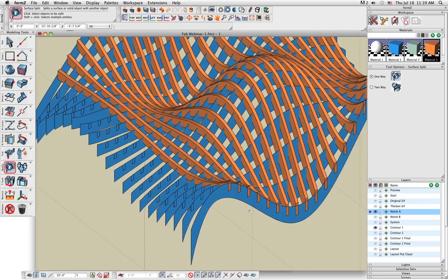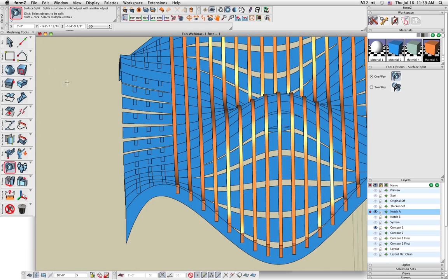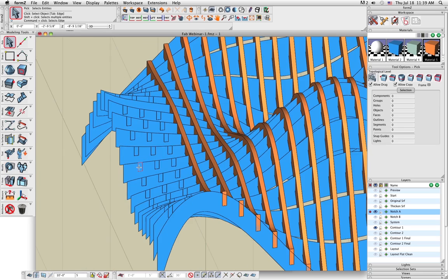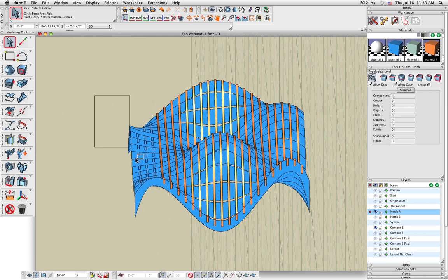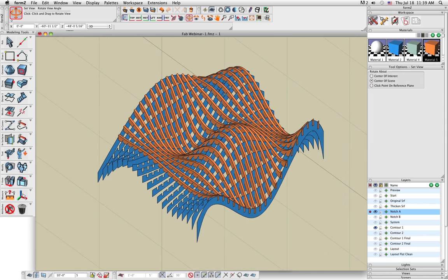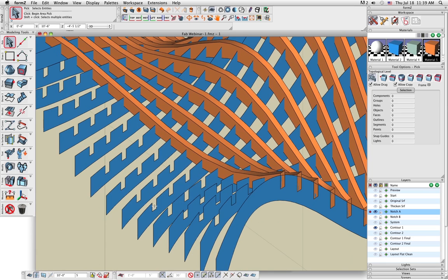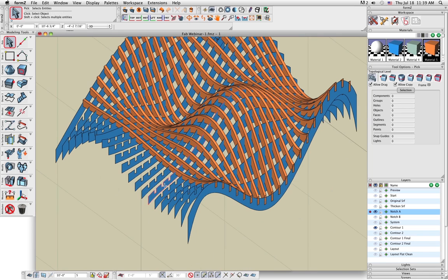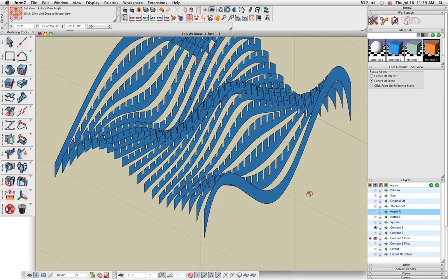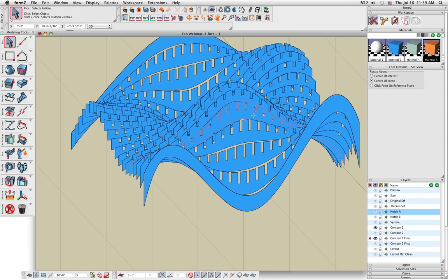and the result is that it will trim off all the pieces that intersected the contour 1. So you see here, all these are now individual pieces. I can just window across all the pieces and delete all the pieces I don't need. So as you see there, those are all our notches that we need for our contour 1. I have a specific layer here where I already did the process. So we have half of our pieces that we need.